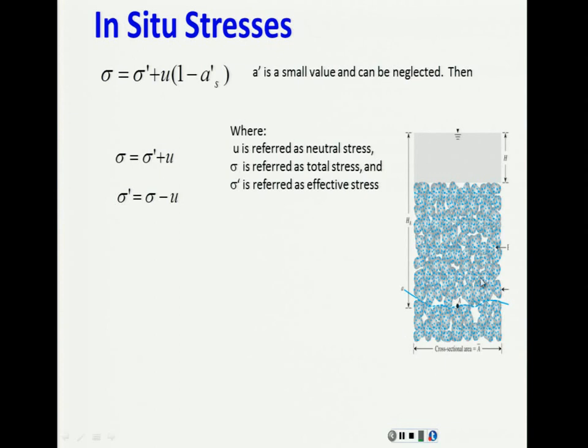The contact in between the grains. That's the important part. If those grains slide in between them, you don't have the necessary contact, you don't have that stress, you will have settlements there also. What is resisting the total weight of the structure that you can place a foundation on top of that is directly linked with the effective stress, not with the total stress, not with the pore water pressure.